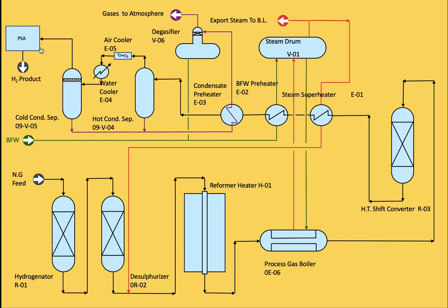Okay, we have here some tips, like the temperature, for example. The inlet temperature of the reformer, as we mentioned, is 550 degrees C and the outlet temperature is between 800 to 900 degrees C. Okay, what is the furnace flame temperature? Near 1000. Okay, the pressure. The pressure for this reaction is typically between 20 to 30 bar. A higher pressure reduces methane conversion but is required for the downstream unit for sure.